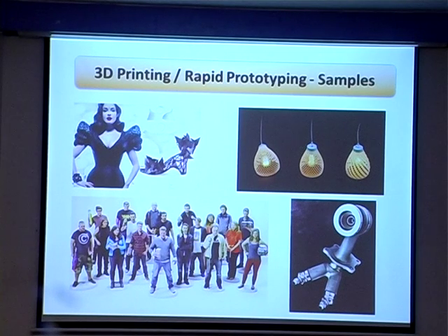Now this is a metal printed nozzle, and one of the advantages in this particular design is it has eliminated 18 individual parts and a single part is made, and it has saved 40% in terms of weight, and the performance is much better than the entire nozzle assembly which was previously being used.